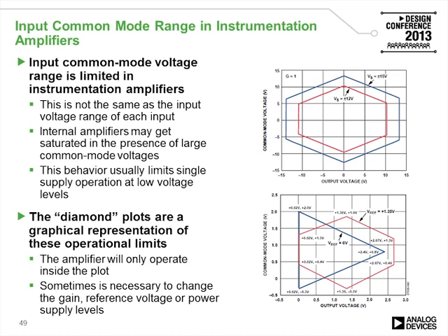In this case, if we would like to have a voltage at the output that is between plus and minus 10, and we have a supply of plus minus 12 as seen on the top plot, we need to have a common mode voltage at the input that does not exceed roughly plus and minus 4 volts. Exceeding this common mode voltage would limit the swing of the output voltage, even if it hasn't reached its maximum value. Diamond plots are very useful in determining what is the valid operational range of an instrumentation amplifier.